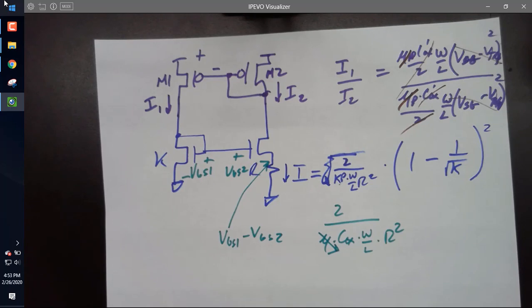If they drop too much, transistors are going to stop behaving like switches, they're going to be leaking like crazy. Your phone will stop working. Okay? So that's the way you remember the threshold voltage goes down as temperature goes up, because if it's going down, the threshold voltage is going to start causing the transistors to leak. If it goes to 0, then you're going to get a current flowing with no voltage applied. Okay, so your phone stops working.